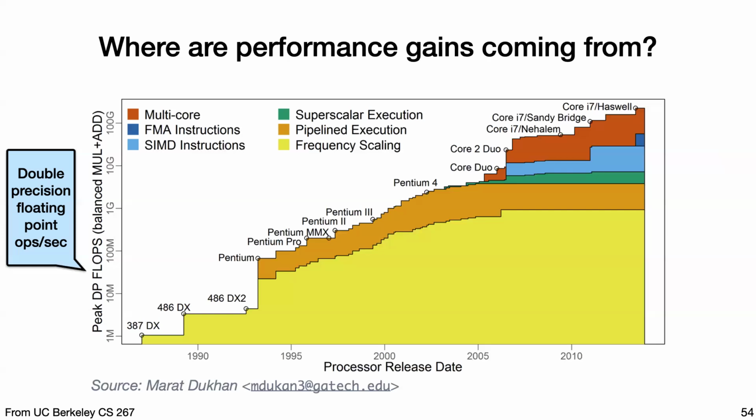Is power a limiting factor? I saw a couple of slides ago that it said it's cores times frequency. So between cores and frequency, is there one which has improved more? Nowadays people are mostly improving cores, because power grows more with frequency than with cores. But for a while, until they ran into these physical limitations, the only increase was in the frequency.